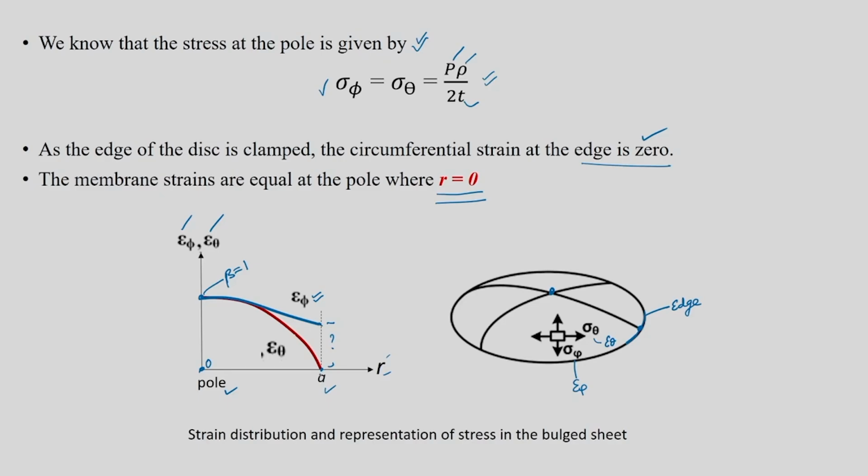Which means when you do a fluid-pressure-based deformation of sheet, which is equivalent to a totally frictionless case, there are chances that your surface in-plane strains are going to be maximum at the pole region, and diminish when you move away from the pole.